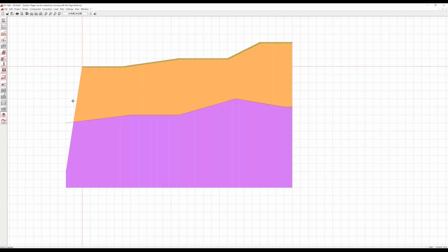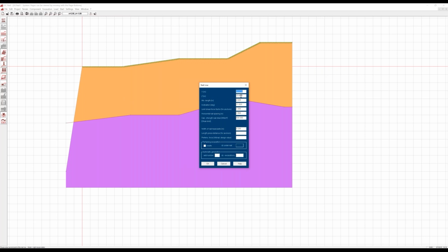Now, after the shotcrete wall, we define the first layer of soil nails. So, for example, here at this position, with a certain inclination, this should be, for example, at a depth of 0.5 meter. We can define the minimum length of the soil nails. Mostly this is a minimum of 3 meters. We have a certain inclination of the nails. Usually they are rectangular to the shotcrete wall. So this would be an inclination of about 10 degrees here.